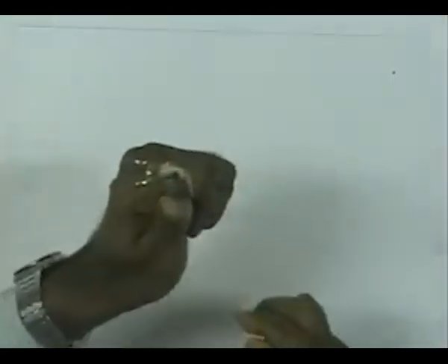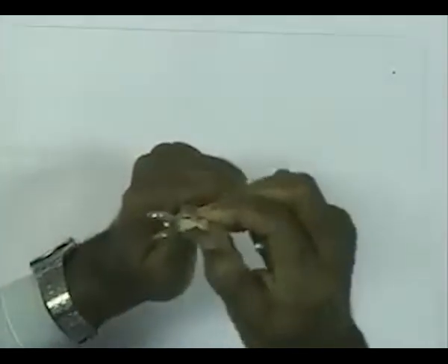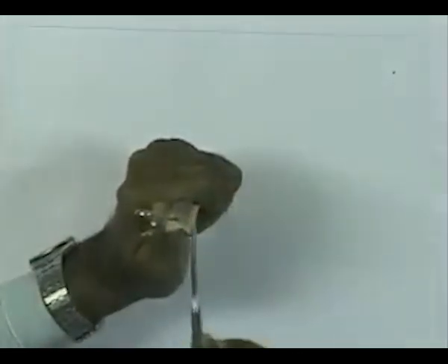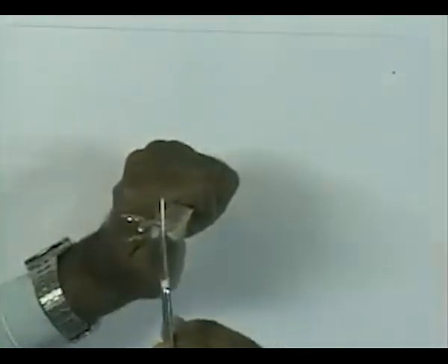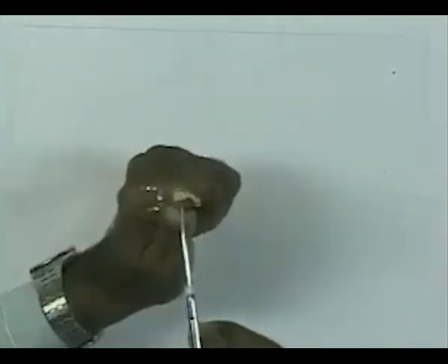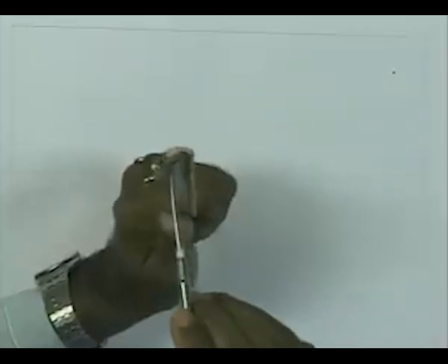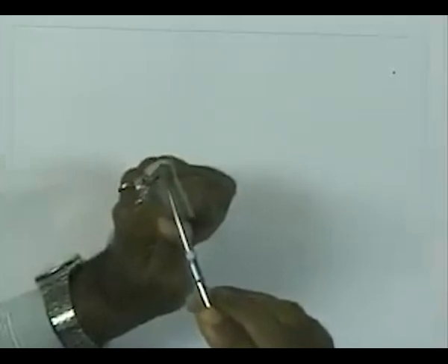I will show you another example which is going to show what shear center is about. So, consider this case. I have a section here, this is again made up of plastic, which is like a C section. I have put some paper inside, that is all, so it does not have any stiffness. Therefore, this is one of the axis of symmetry, and this is the other axis which is not a symmetric axis. Now I put a load there. If I put a load there on the cross section, you see it is twisting. I put a load there, at this point it gets rotated.